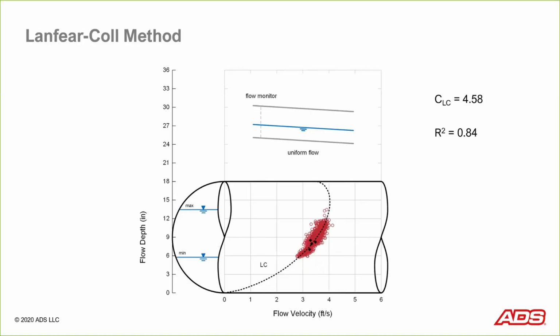What it does is it really takes the Manning equation and operates it in reverse. They were doing some work in streams or channels, and they would go out and do a point measurement of depth and velocity, or get some profiles done. They would say, okay, I have a depth and velocity data point. Let me draw a Manning equation through that data point. They were basically doing this without having direct knowledge of the roughness or the slope of that channel.